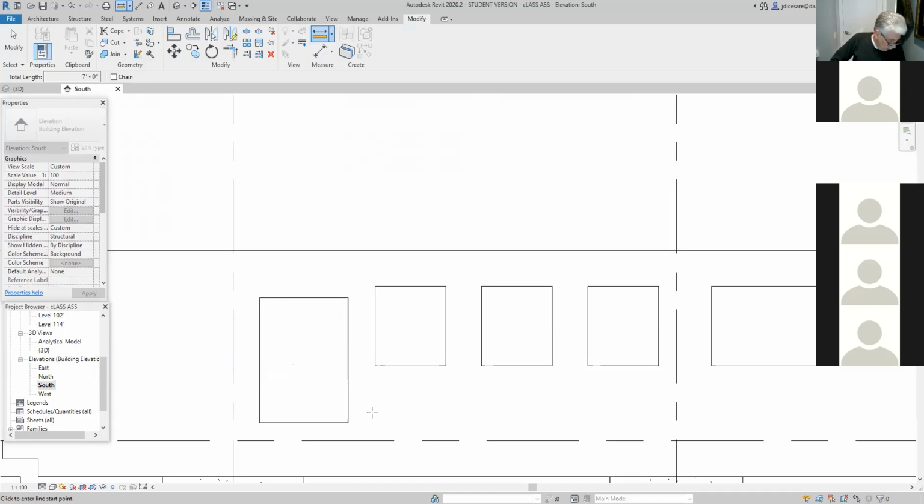Okay. What height is the slab at? Well, if you look, if you go to where the stairs are, Jimmy, you see that you have 9 feet 4 inches plus 6 inches. That's where the slab is. So that's 9 feet 10 inches. Yes. Okay, so what's 102 feet minus 9 feet 10 inches?